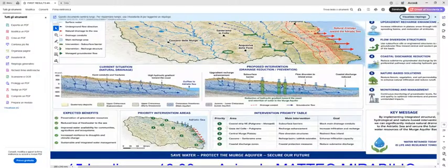Cassano, Santerno area: recharge basin, sinkhole. We also have the trouble of sinkholes, and the stability of some karstic conduits, so this can also be addressed in other parts to solve the sinkhole problems. So the goal is to enhance the infiltration capacity. Coastal discharge zone: the main intervention is a coastal protection measure to reduce submarine discharge.